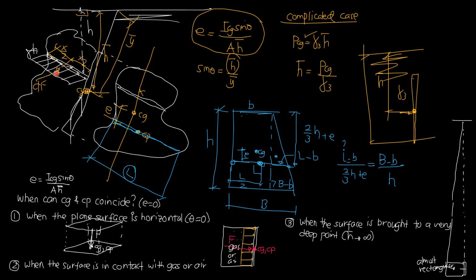The differential force over that strip is therefore acting through the centroid of this pressure diagram. Since the pressure diagram is rectangular, it is natural that this dF passes through its centroid. So if in general the length of this strip is x, then dF is acting at half of x, x over 2, because this is a rectangular pressure diagram.